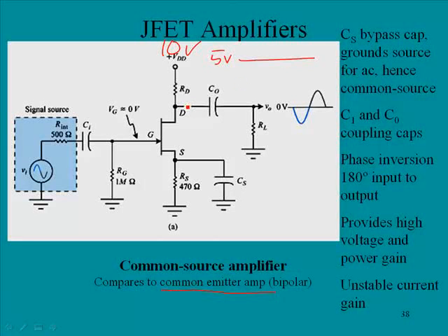And so the output that's developed here, the AC, is going to be at a 5 volt level. If you were to look at an oscilloscope, you would see 5 volts here, but at that 5 volt level you would see this AC signal riding there. Now, the reason that you have this output coupling capacitor is that you do not want that DC on the load. Remember that a capacitor does not pass DC, only AC, so the AC signal is passed across the cap and goes to the load, and notice the reference here at 0 volts.